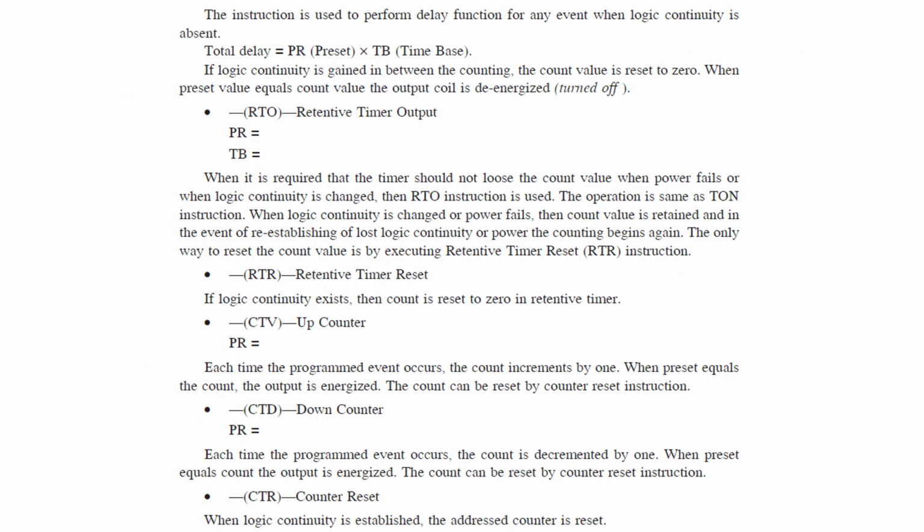In addition to the on delay and off delay timers, there is another timer called a retentive timer. When it is required that the timer should not lose the count value when power fails, we use the retentive timer. The operation is the same as the TON instruction. And there is a retentive timer reset: if logic continuity exists, the count is reset to 0 in a retentive timer.